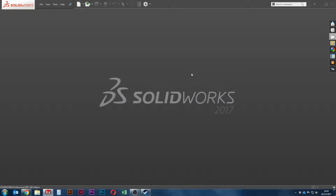I think one of the best ways of doing it would be to create a sketch of the slots that you use, if you have standard ones, and then put them in the design library, so you can drag them in every time instead of sketching them. That's the only quick thing I can possibly think of. In fact, I'm 90% sure that's got to be the case. I think you've got to create them as a sketch and save them in the design library.